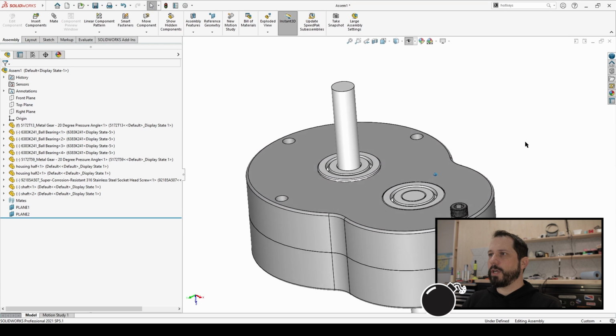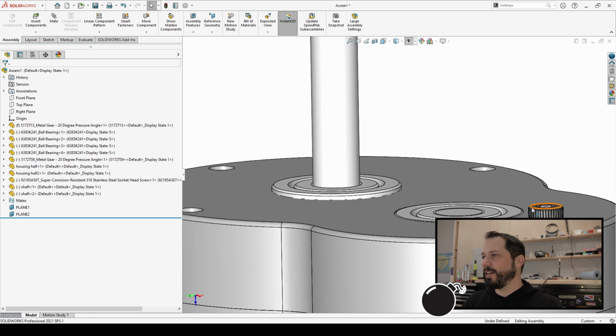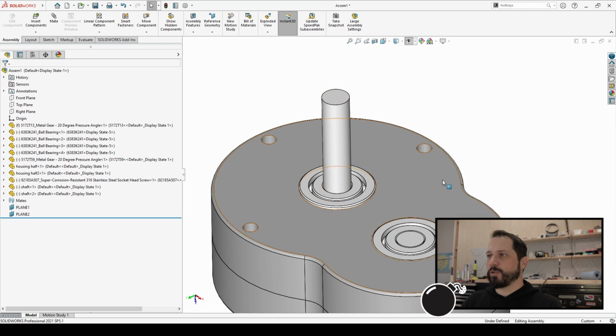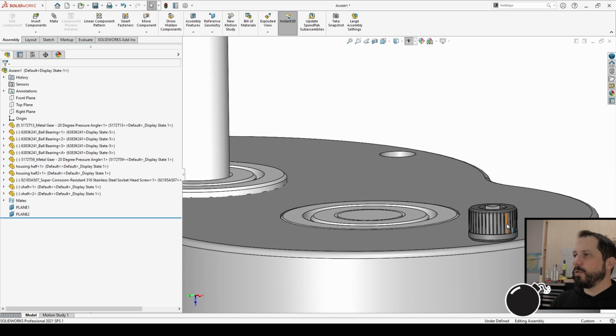Okay, another one I use all the time, and I've seen some people's jaws drop when they see it. I know mine did the first time I saw it. If you have an assembly and a bunch of screws, there's only 4 here, but sometimes there's a ton of washers. What you can do is, if you can get to the bottom edge of the fastener like this, really easy for a washer, sometimes a little trickier for fasteners, before I click on it, I'm just hovering over that edge. I hold down Control, and then I click and drag from that edge to any diameter or any hole feature,